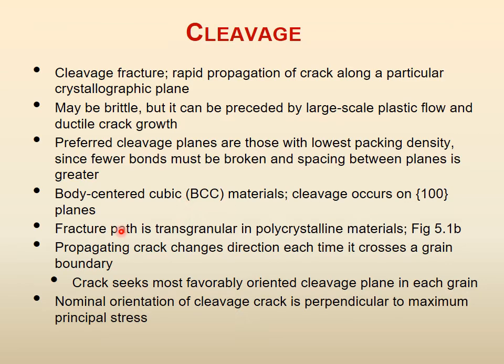100 planes. The fracture path is transgranular in polycrystalline materials. This is major. Transgranular. You see, intergranular means along the grain boundaries. It does not break from one grain into the other grain. But transgranular means it breaks from one grain into the other grain. So this is large, and that is in normal polycrystalline material. So we will go to the figure and show you that.